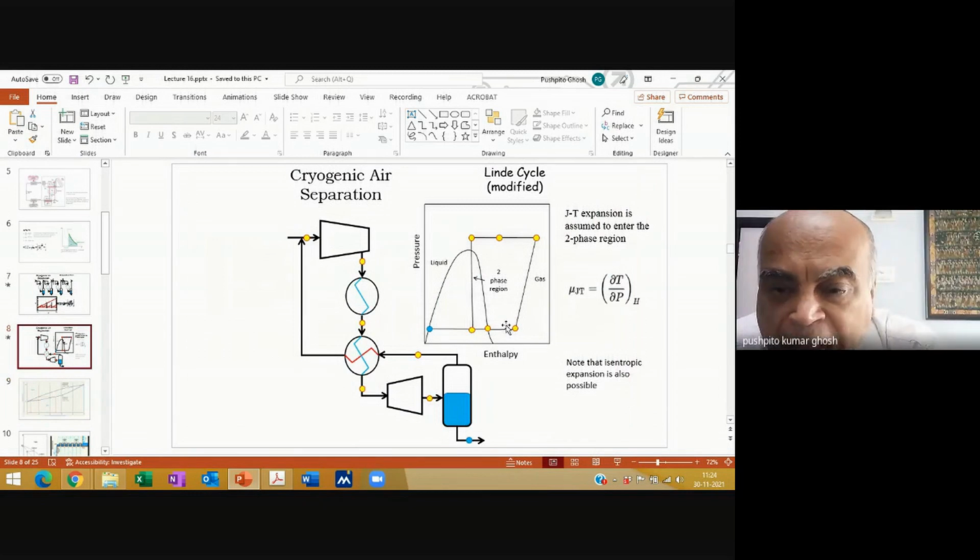Sure. I'm starting with a gas over here. Let's say this is the enthalpy of the system. Now what I'm doing is I'm doing external work and I'm pressurizing it. Now when I pressurize the gas, and it's a real gas, because of the increase in pressure, of course, because I'm doing work, my pressure is increasing, but so will there be an increase in temperature.